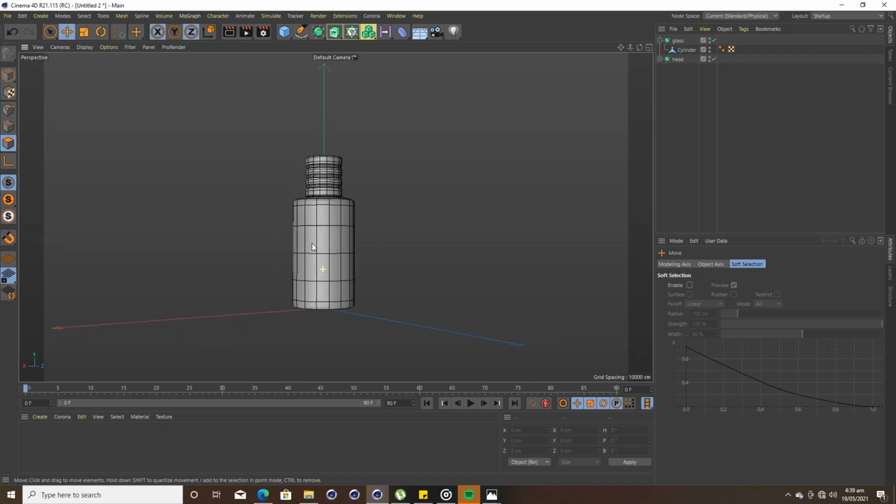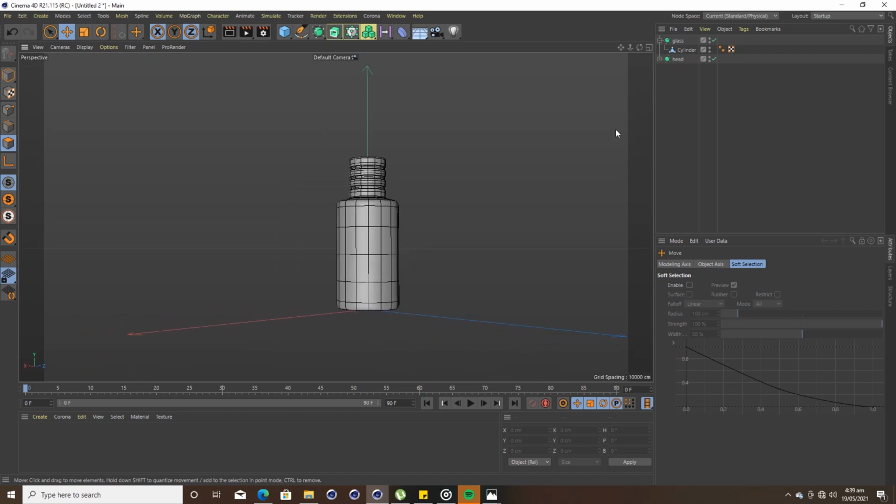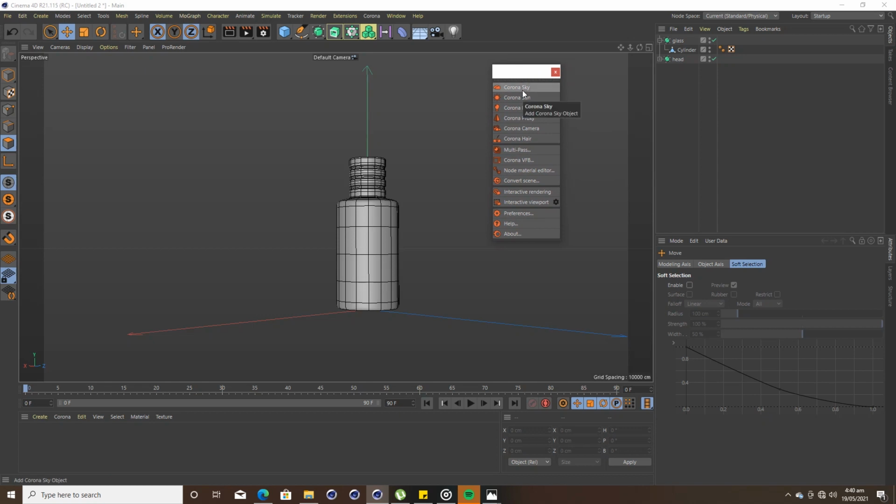With my process of lighting, what I do is I create a very simple Corona Sky. So let me just bring the Corona tool set here, undock it and bring it down here. What I do is I create a simple sky, and I use the sky to texture my products. I don't really pay attention to the lighting setup, just something that will lighten my scene up to be able to see my textures, and I'll work on the texturing, I'll work on the shaders, and after that I can work on my lighting.